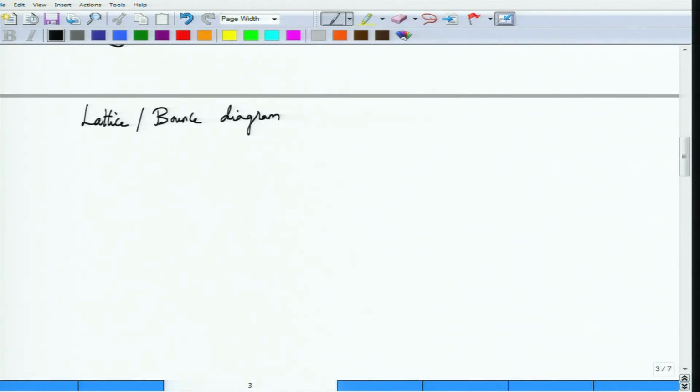So what is this lattice or bounce diagram? The idea is simple. You have a source side, and there is something that is happening along time. So this vertical axis down is the time axis. Sometimes you find in literature that time is normalized with respect to the delay time of the transmission line. You can do that or you don't have to, there is no problem. So let us call this time either absolute time, or one can imagine a time delay normalization, you can do that as well.